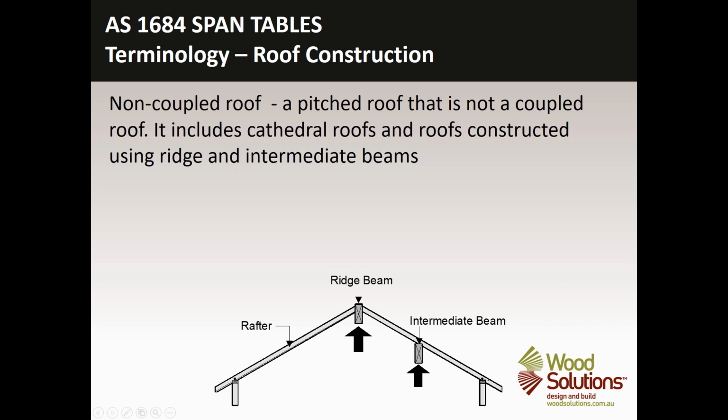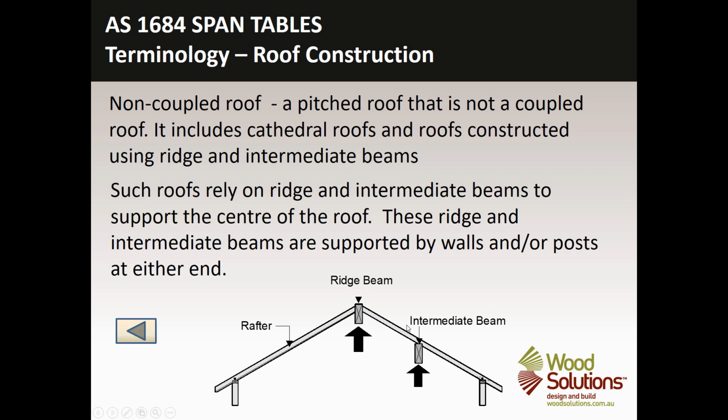And of course, this requires a very large beam because it has to make a very large span. It depends on the run of the building. And then also, to minimise the depth of the rafters, you can provide an intermediate beam doing the same thing.